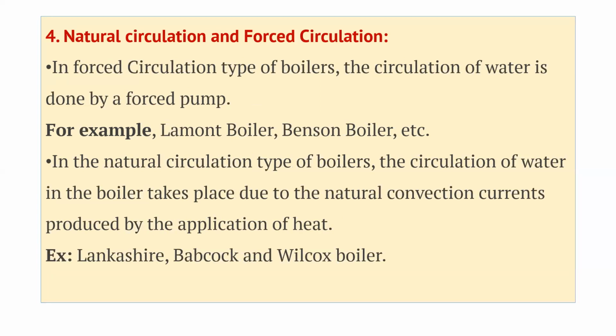The next parameter for boiler classification is natural circulation and forced circulation. A boiler means we are taking water and heating it, right? Now, if we make the water move by some external device called a pump, it is called forced circulation. Suppose we are moving the water with some external device, either manually or by a pump, it is called forced circulation.